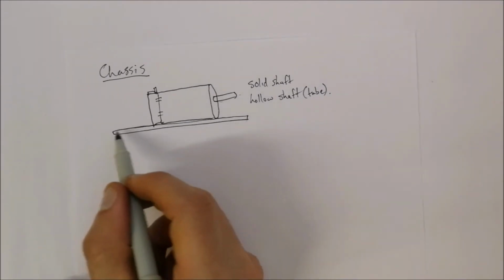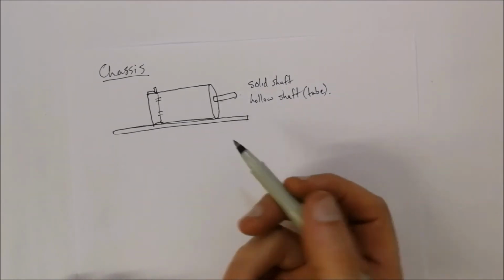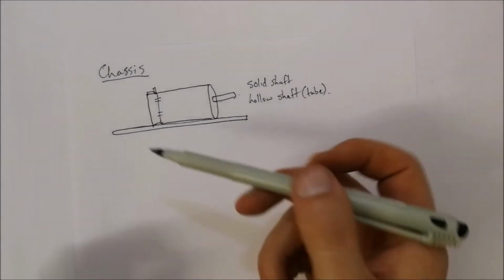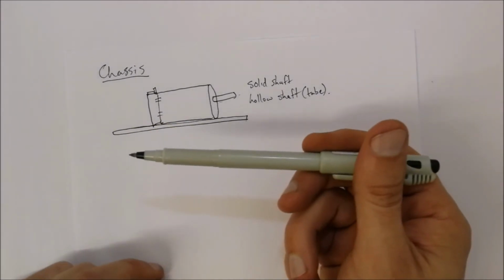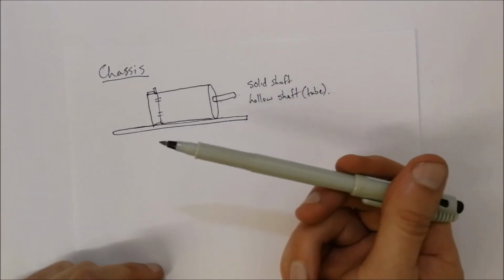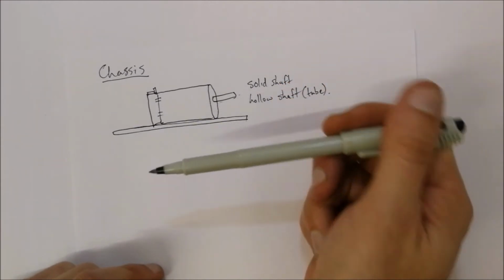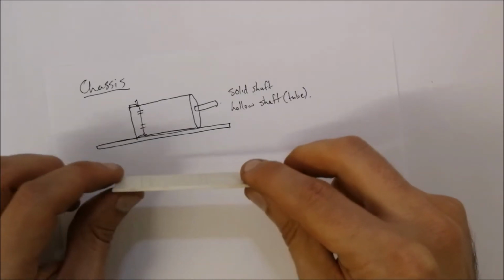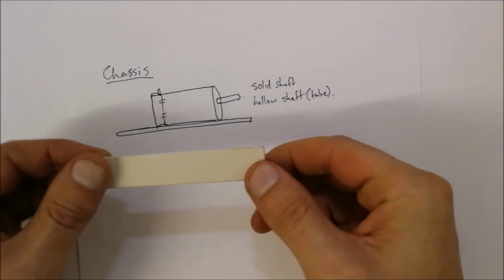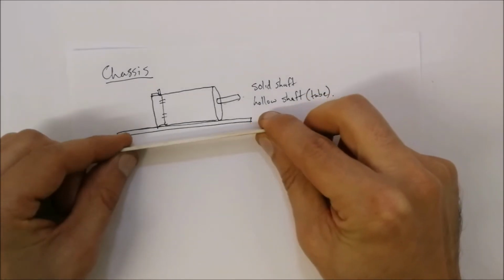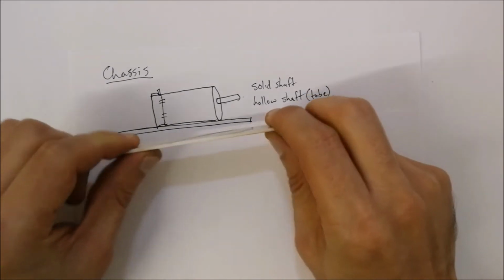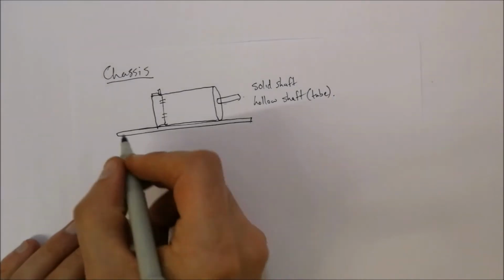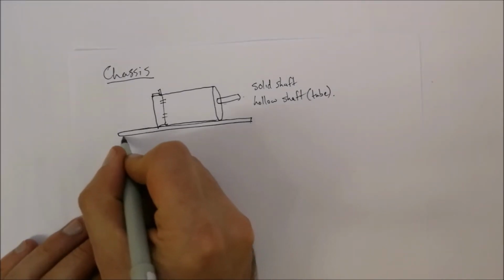For the flat bar over here, you might feel that a sheet of mild steel might work. But the problem with a sheet of mild steel is that there is a possibility of it warping upwards or downwards. Bending is able to happen, because essentially that flat sheet at the bottom is like this piece of plastic placed in this position, and you will be able to bend it upwards and downwards. So maybe for that reason, you need to put some supports at the bottom.